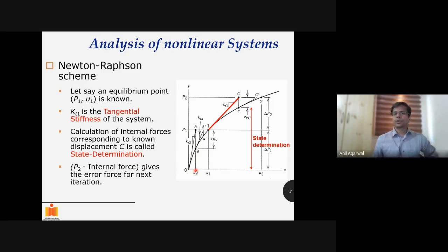But now comes the trick. What will happen is that as you apply that force P, you will assume that you have applied full force P and you will get a certain deflection. Then you look at that deflection, and for that deflection, you work back what the force in the spring is. And what you will see is that the spring has not developed this much force, but only this much, because along the way, it bent downwards. This curve did not continue on this path, but it bent downwards. That means it did not develop all that force. It developed a smaller force. And as a result, there will be an unbalance.